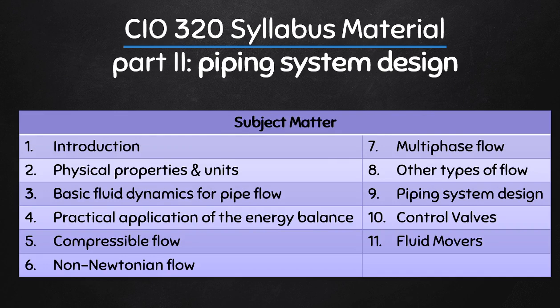For piping system design, we will go over the physical properties and the fluid dynamics, which you are already familiar with, and also the pipe flow concepts before getting into the practicalities of actually designing piping systems. The design equations are typically based on the mechanical energy balance. It looks reminiscent of Bernoulli's equation almost, but there are some bits that we add to it.